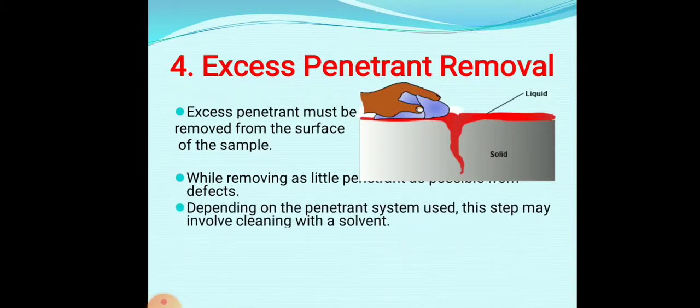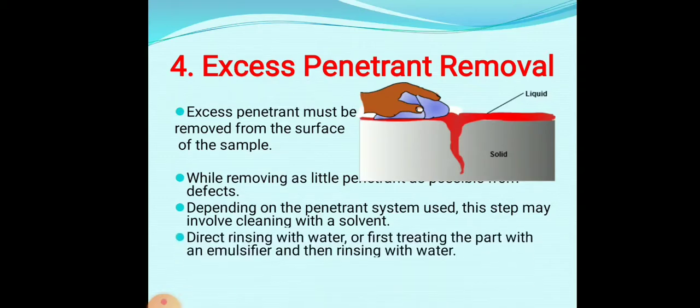Depending on the penetrant system used, the step involves cleaning with a solvent, direct rinsing with water, or first treating the part with an emulsifier and then rinsing with water.